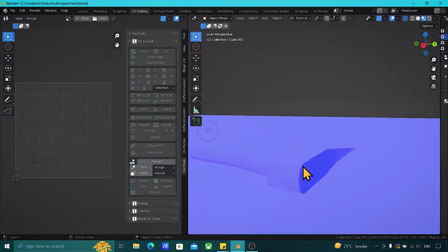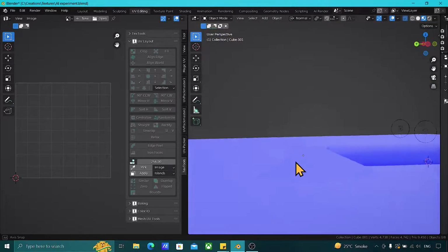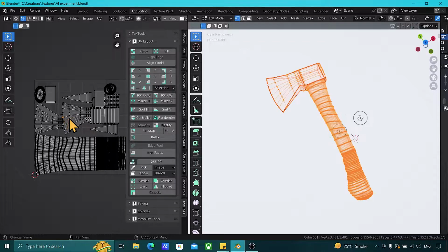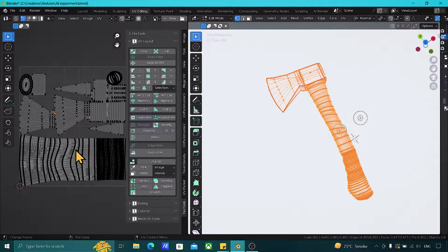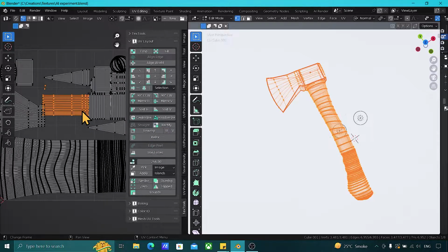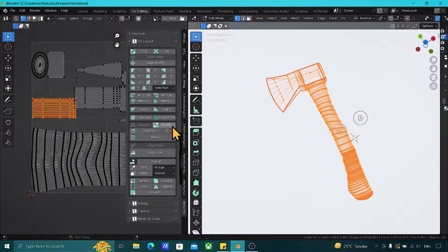All right. So make sure that your blue is always outside, and the faces that are outside of your mesh are properly blue in color when you turn on this overlay. You need to check whether all of the textures are properly managed. So firstly, let's correct the orientation. All right. So press L, press rectify. You can see the exact formation, because it won't be stretching the UVs in this manner. The UVs will get stretched, all right, because the shape is scattering like this. So just press L, rectify.